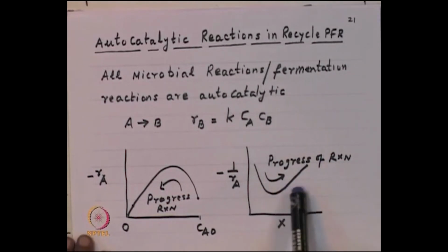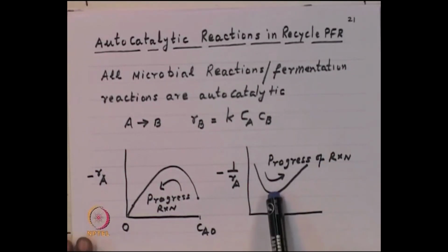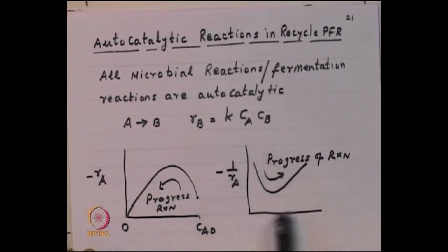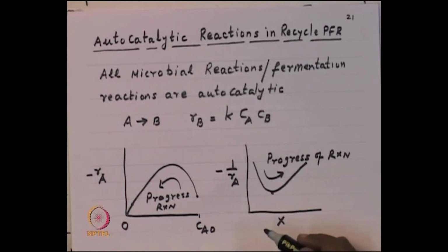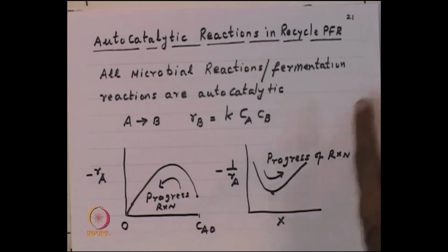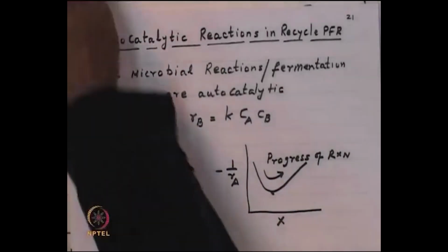Okay. So, this feature of maxima in reaction rate, or minima in this kind of plot, is useful in design, because if you can design your system at this point, your reaction equipment volumes are very low, lowest, because the reaction rates are very high. So, there is an advantage, but at the same time the disadvantage is that the conversions may not be high enough. You see various issues like this, which become important in design. Having said this, let us just look at this in some detail.